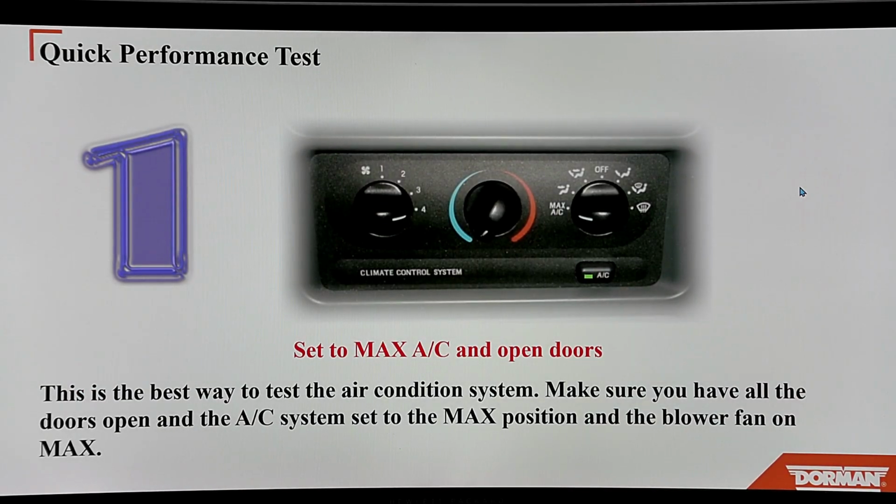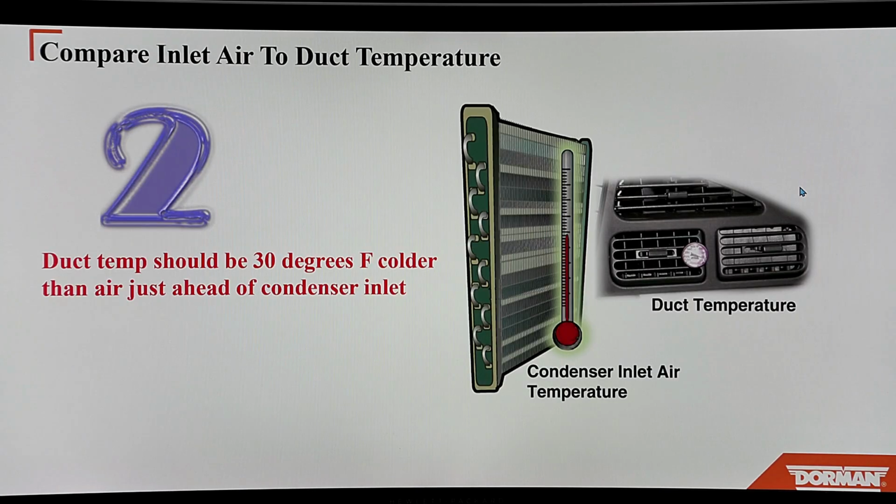Now, quick performance test, because we're almost at the end, and I don't want to interrupt more of your lunch. You set it to max AC, open the doors. This is the best way to test the AC system. Make sure you have all the doors open, AC set to max position, and blow a fan on max. This is going to make the system work really hard, okay?